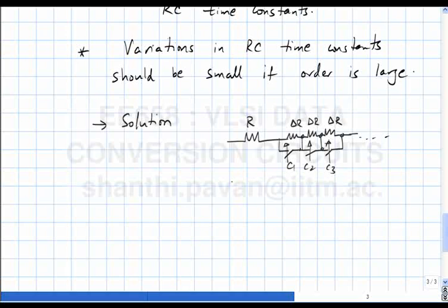So in this particular example, the resistance varies all the way from R to R plus 3 delta R, and you have to choose R and delta R intelligently to make sure that in spite of R varying by plus minus say 20 or 30%, you should always be able to find some digital code which will bring the effective R back into a range which is acceptable for the modulator. Does this make sense?